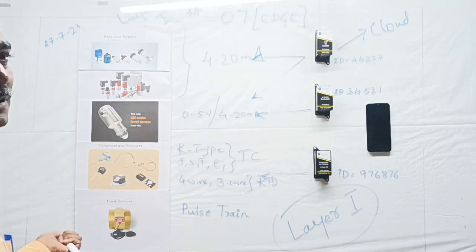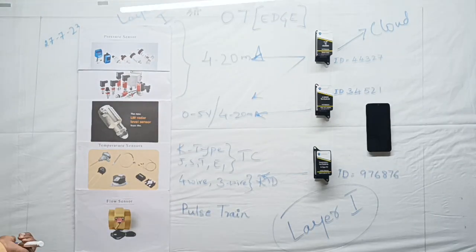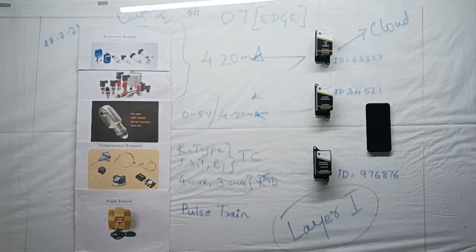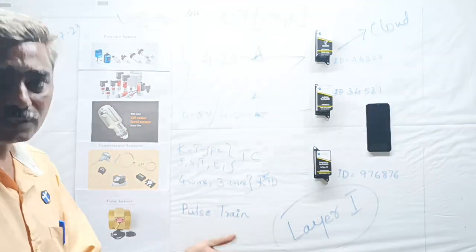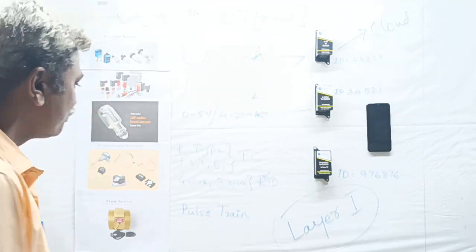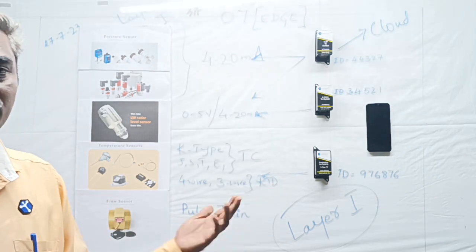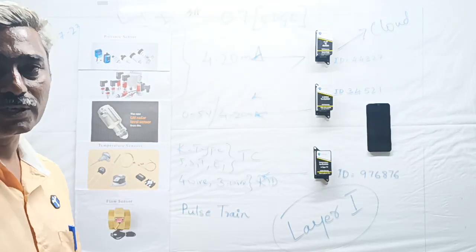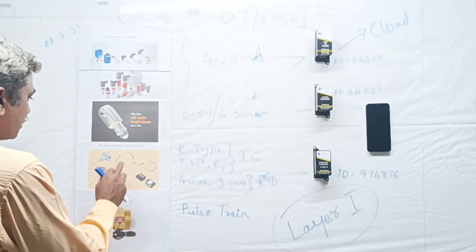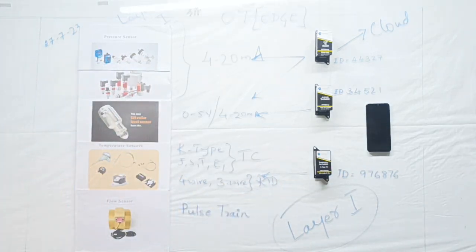I don't remember the name, that gives you negative values. DS18B20. Yeah, DS18B20. That gives you negative values of temperature, meaning sub-zero temperatures. Like if I want to monitor a freezer or a server room where things go below 0 degrees. So all those types of temperature sensors also get connected to the edge devices.